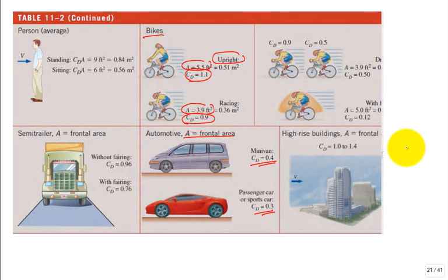But you can work a lot, and maybe you had a vehicle at 0.5 and want to get it to 0.4. A little bit of streamlining will do it. 0.4 to 0.3, a lot more work. To drop it from 0.3 to 0.2, you're going to do a lot of work. I think a lot of vehicles are at 0.2 to 0.25 in that vicinity, and it's too much work to drop it lower. You need a mirror for safety.